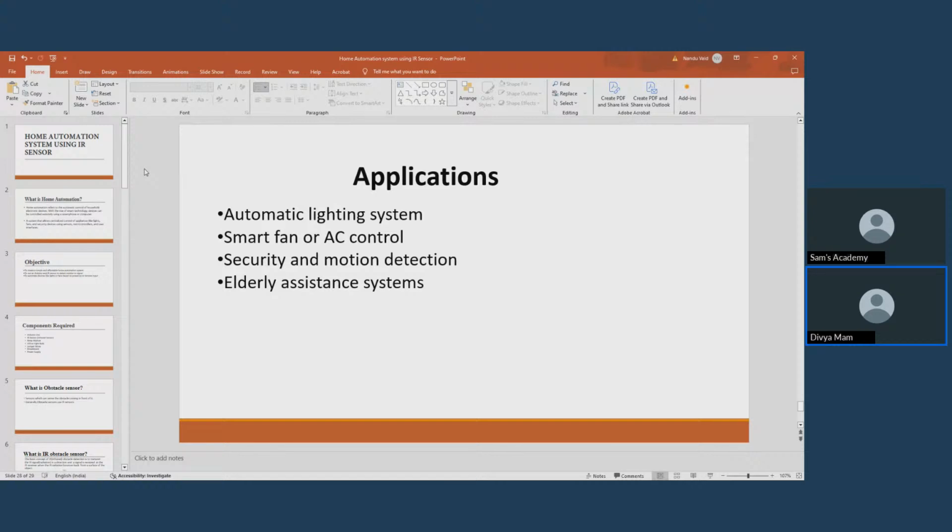So we just took the relay generally in Tinkercad, whereas the model will be different, when I showed you the model, right? The model has 3 pins, and there are 1 channel, 2 channel, 4 channel and 8 channel modules also. With a 1 channel module we can connect only one device, only one LED, 12V LED or a motor. If you use the 2 channel relay, we can control 2 devices separately. Whereas with the 4 channel relay, we can control 4 devices, and with 8 channel, 8 devices. That's it.